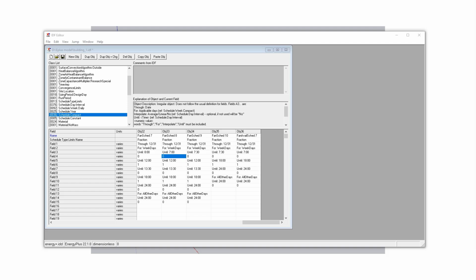For example, is it a holiday? Is it the weekends? Or are we talking about the weekdays? So this pattern is controllable also. And there also are seasonal adjustments. So we can say for winter days, this will be the schedule. And for summer days, the second schedule will be set.